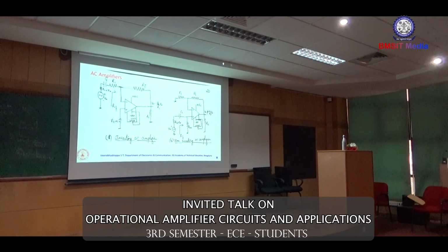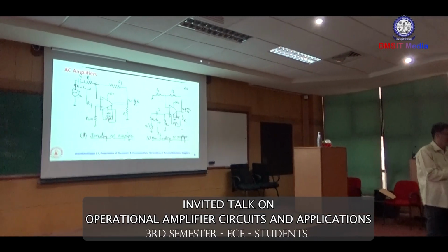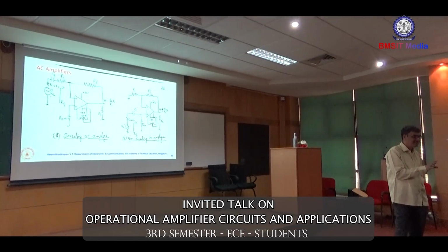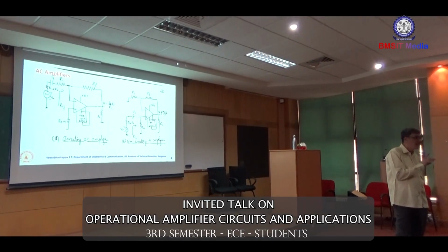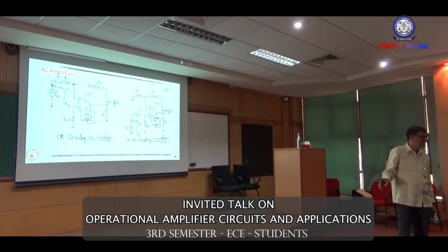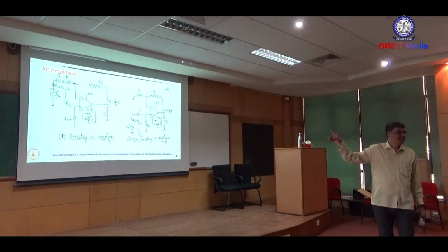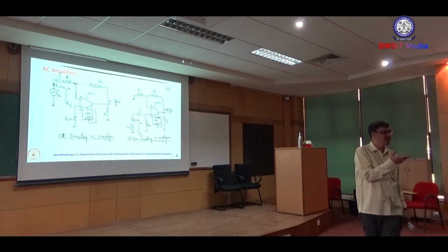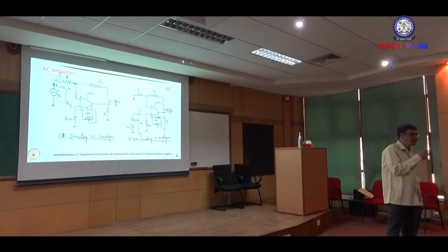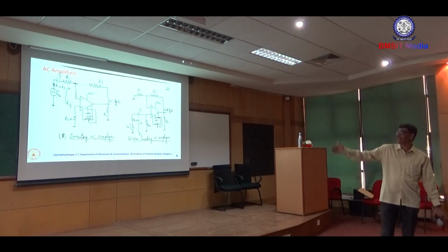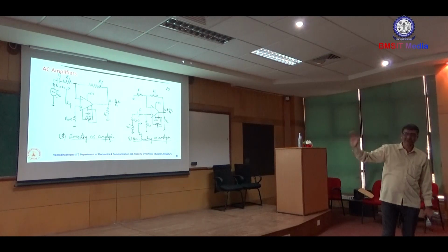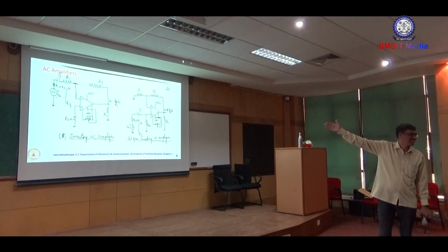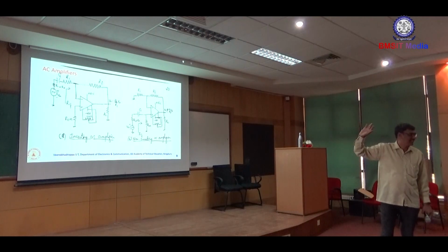The output resistance of a signal generator is given. This matters for impedance matching, so you should use a proper probe. That resistance is about 60 ohms in the case of a signal generator, and for the CRO it varies from 60 to 600 ohms. If you have not observed, when you go to the lab you have to check it. The output resistance of the signal generator, that is Ri or R0, is negligibly small when compared to R1. Therefore, you can neglect it.